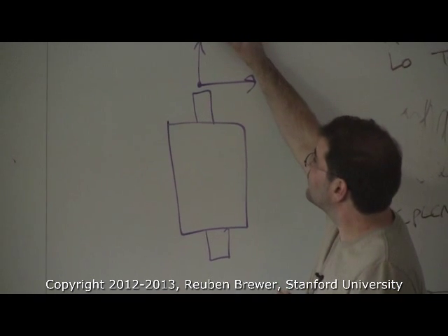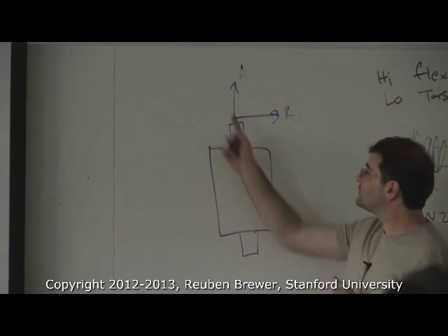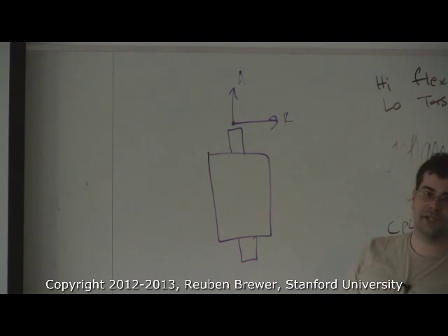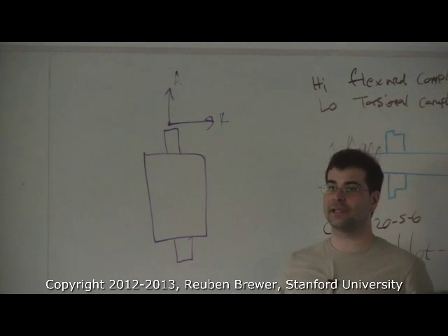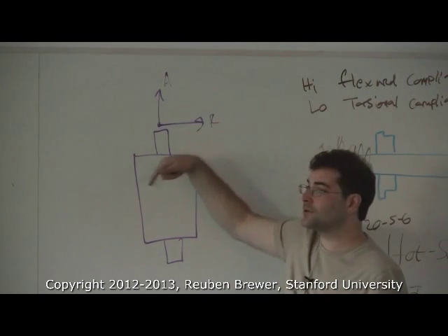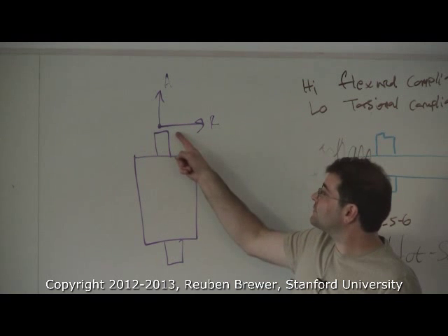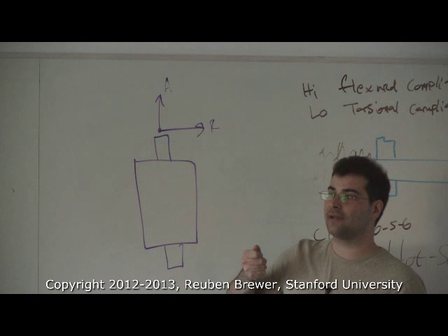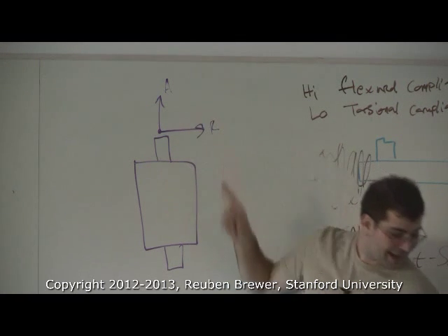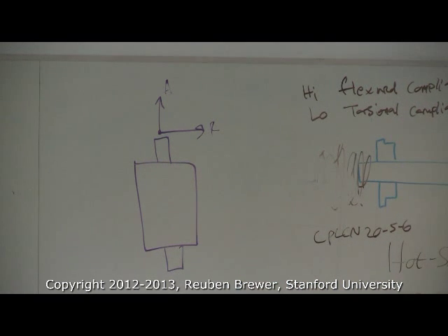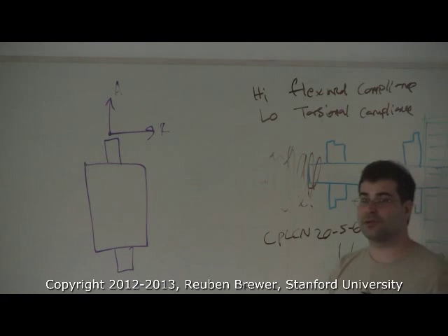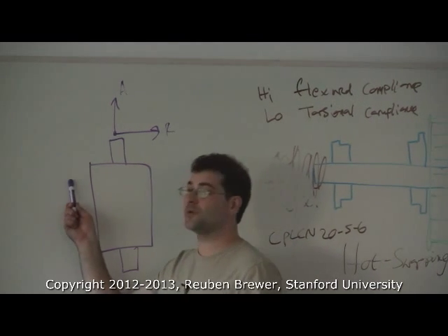Radial, axial. Axial, unless you're doing something odd, say a big helical gear that gives you an axial thrust load, you could have that. Mainly this is for press fits. When you're hammering on a press fit, A, don't do that, and B, it will break your motor because it'll exceed your axial limit. For an RA30, it's 5.6 newtons. That's pretty low. You're going to do a lot more than 5.6 newtons putting a press fit on. So if you try to press fit directly on the motor, it'll break.